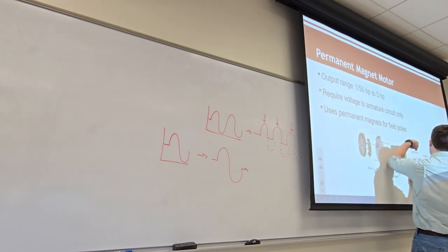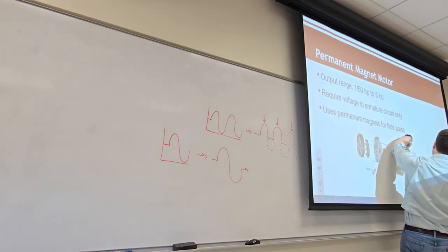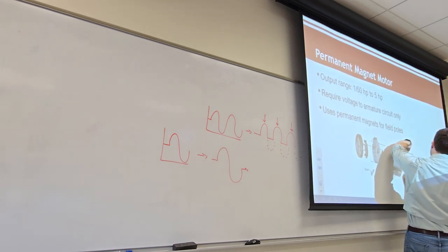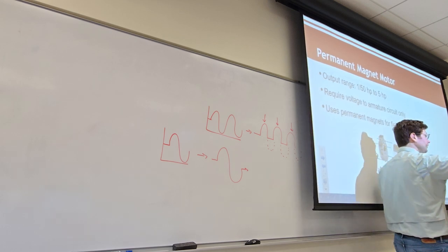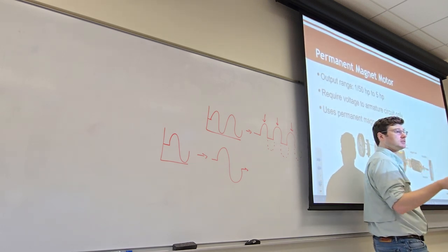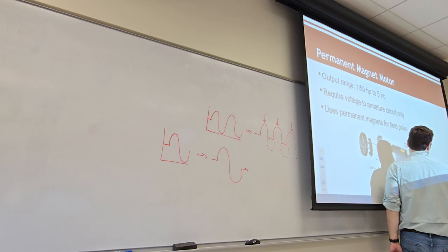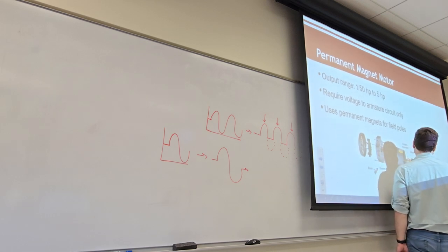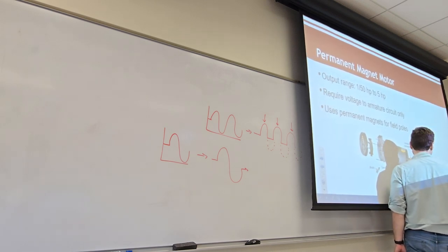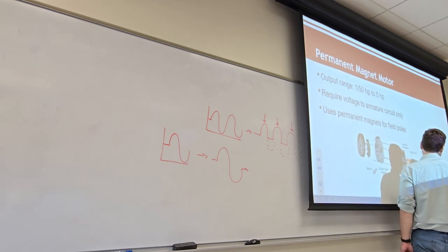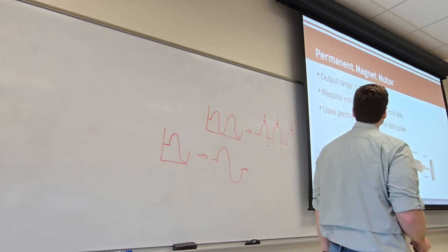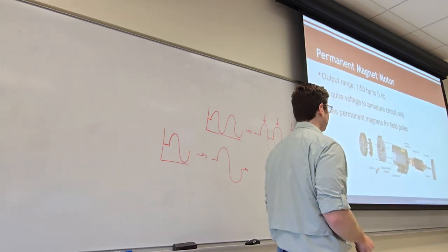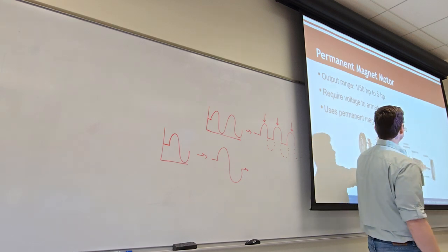So if we have wipers, right? If my fingers were graphite that could conduct electricity, right? And I touch them here, as it turns, I would be connecting to two different sets of coils. And as it turns over, I would be activating different sets as it cogs over. Here are our laminated sections. This is the thing that receives and boosts the magnetic energy. Okay, and then this is just a simple bearing, again, for mechanical rigidity. All that's shoved together in a can, and then you just apply AC or DC voltage to it accordingly, right?